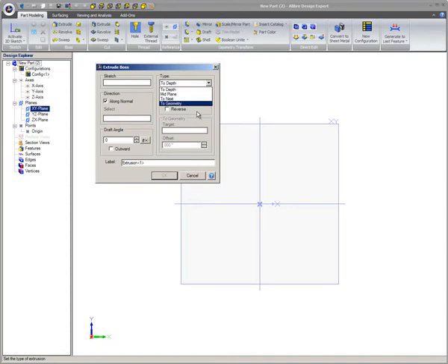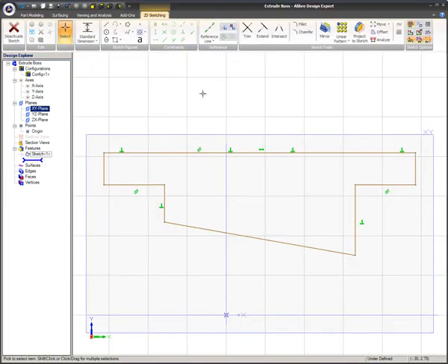To geometry target. When the To Geometry option is selected, this portion of the dialog box will be accessible. When active, a planar face or plane will need to be populated in the target text box. Here is an extrude boss demonstration utilizing this sketch.